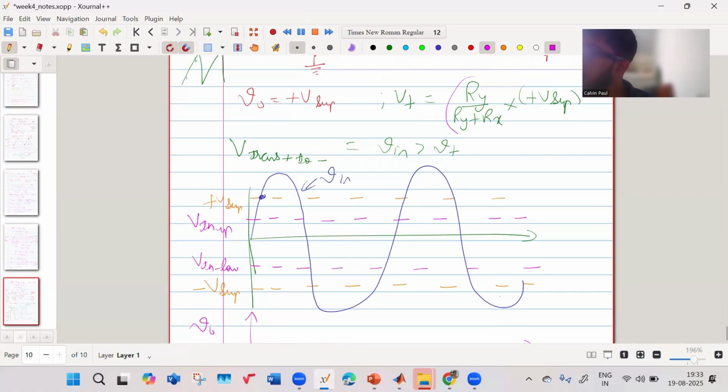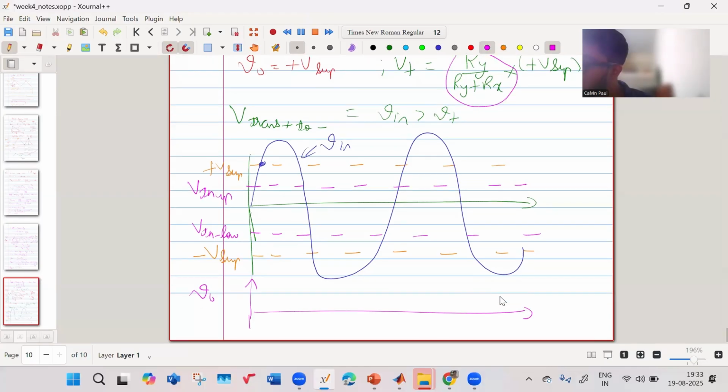That is just a scaled down version of your V supply. So at the instant when it crosses these points, certain things can happen. We have said that my output, assume it is plus, when it crosses this V supply into a scaled down factor of that, my output will go negative. So in that case, it will go negative.